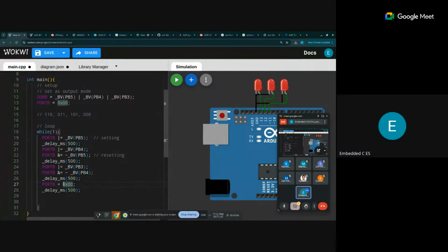How do you just disable these 3? Or here you can just disable this one, as we know the particular thing is there. But how do we only affect certain bits? You just have to OR it or AND it with these particular values. For example, if you want to set multiple bits on, how do you do it? You use an OR.